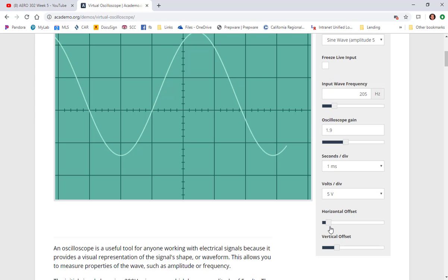2 milliseconds. So each one of these is 2 milliseconds, or each block? It's always in blocks. The dials talk to 2 milliseconds. So how much we got here? 1, 2, 3, 4.9. So I got 4.9, and it was in what? 2 milliseconds. Okay, so multiply it times 2. Again, I'm going to preach this one. Milliseconds. E to the what? Negative 3. Equals, and so I get 0.0098.